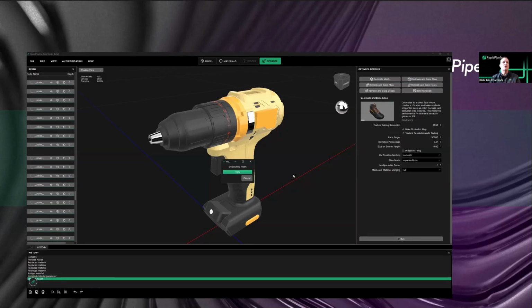So now it's going to go through the process of decimating the mesh, collapsing all these down into a single object, creating the UV atlas so that they all have a unified UV, so they all get unique occlusion baking, lighting baking information. And then it bakes this 4K texture down for us so that we have that occlusion map for it. And then we'll be able to export this out to, say, a USDZ or glTF file and see it in a real-time renderer.